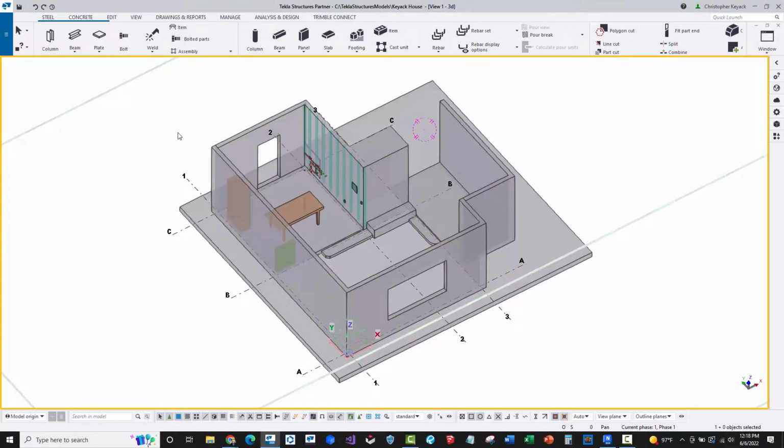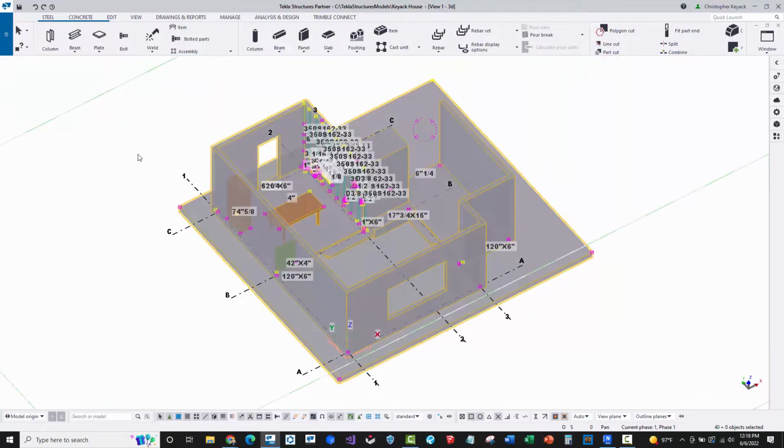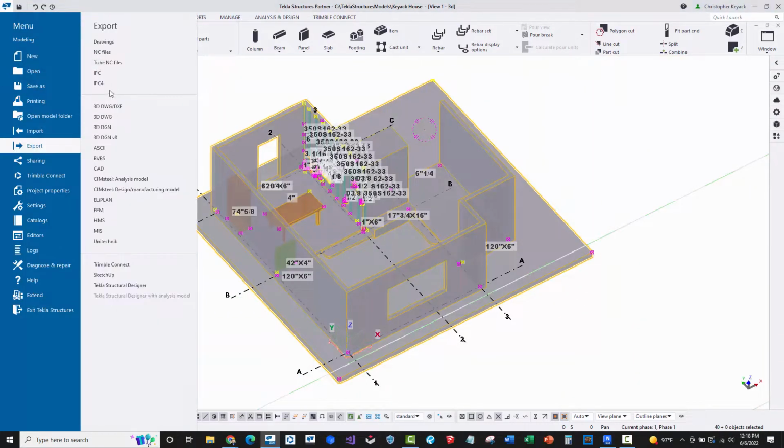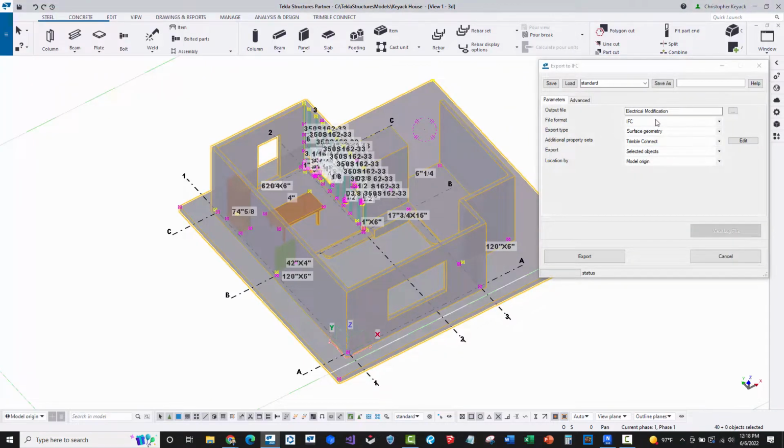Now I'm going to showcase a workflow with Tekla Structures, and I'm doing this on purpose because most of Visual Live's content and tutorials showcase how to export models using Navisworks and Revit. They actually have a direct integration or plugin inside of Revit and Navisworks to publish the models. Tekla Structures doesn't quite have that, but that's okay. You can still select all of the objects in your model and export an IFC file. If you manually create that IFC file, you can load it up to their web portal so the models can be loaded on the HoloLens and your iPad.